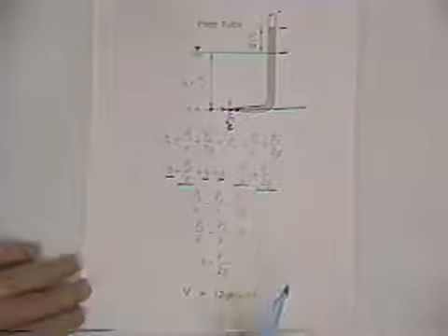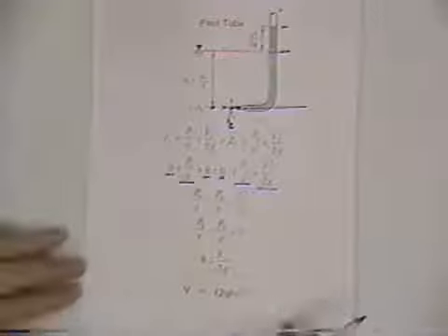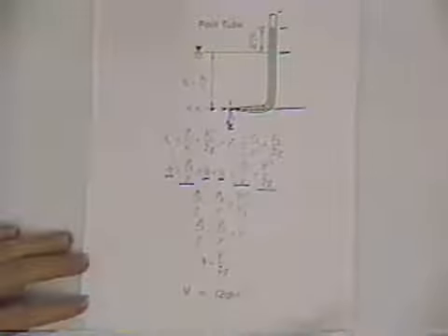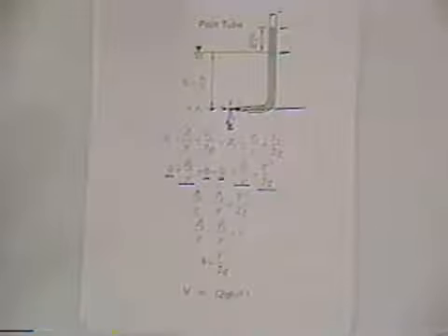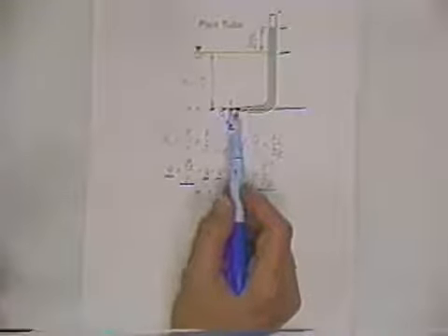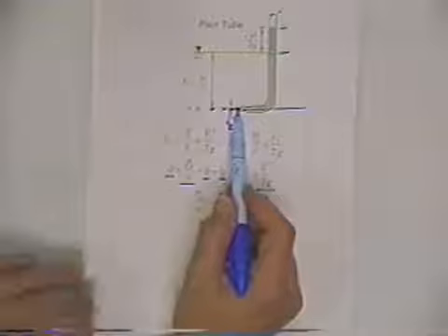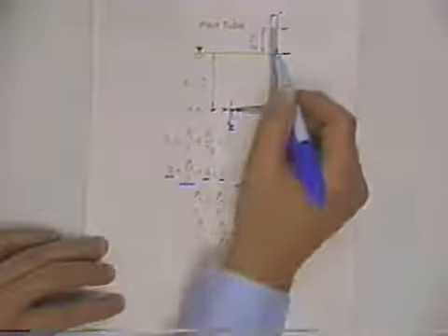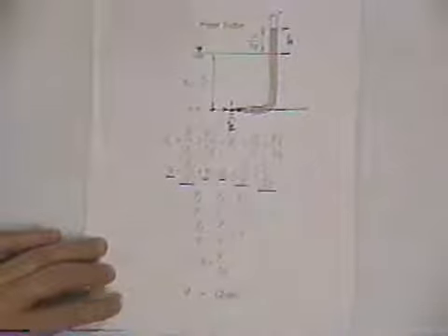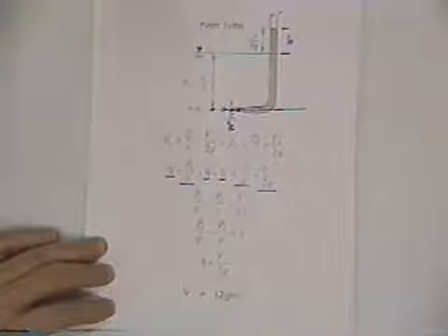And so really, and this is also true of applications in general, what we're doing is trading off between pressure head and velocity head. The elevation head's the same, so we're just trading pressure head for velocity head. Inside and outside, we've lost velocity head as we went inside, and where did we pick it up? We picked it up as an additional head here. That's just additional pressure head that's equivalent to the velocity head that's outside the pitot tube.